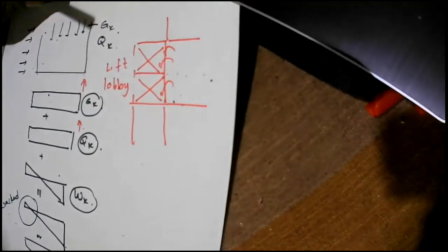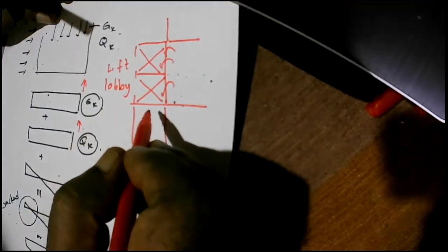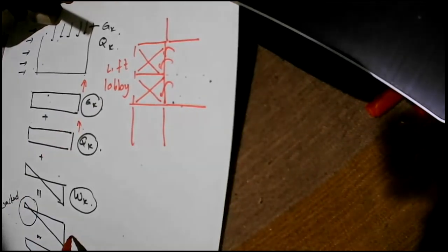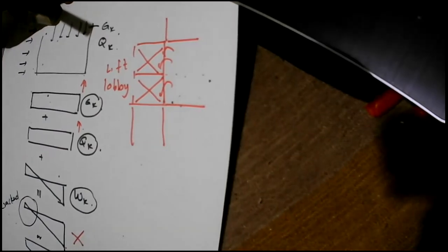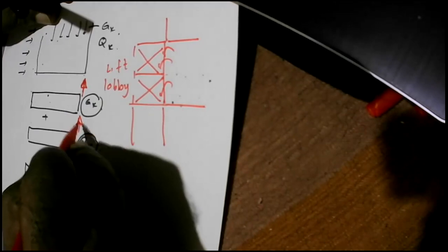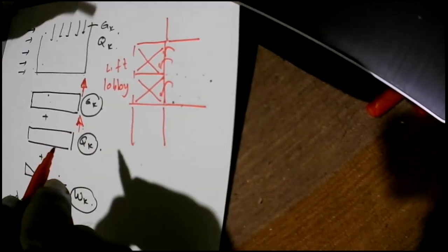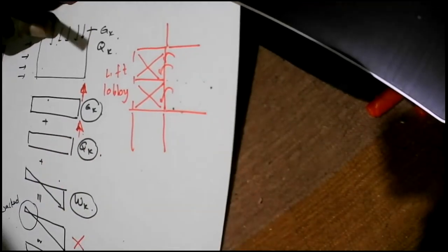But because we are having voids on this side, you will find that the load coming from this side is not high. So if you want to make sure we do not get this type, we have to make sure these loads, the vertical load transferred onto the shear wall, are high enough.